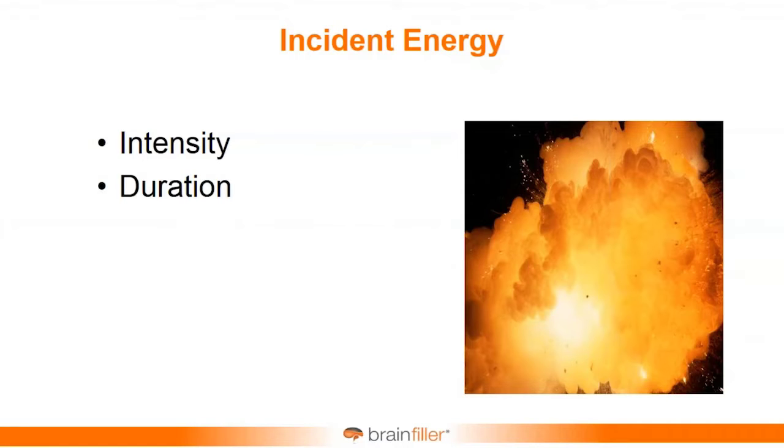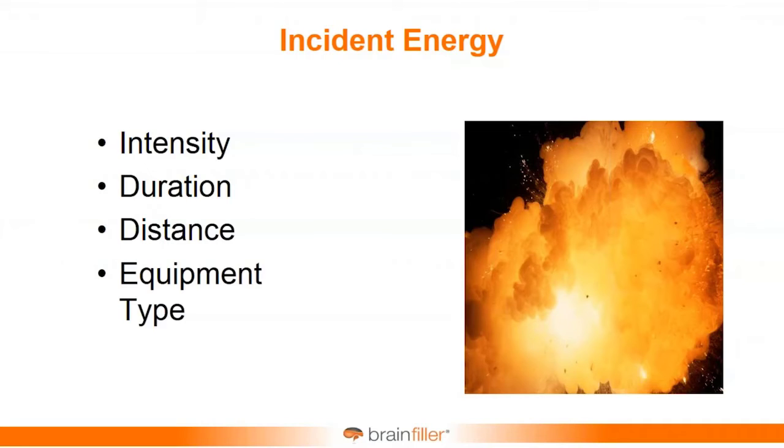The duration is also important. In fact, I would say the duration is probably the most important variable in the whole process, because the incident energy is directly dependent on the duration of the arc flash. Distance is also incredibly important, and this is going to get into the term known as working distance that I'll discuss here in a moment.